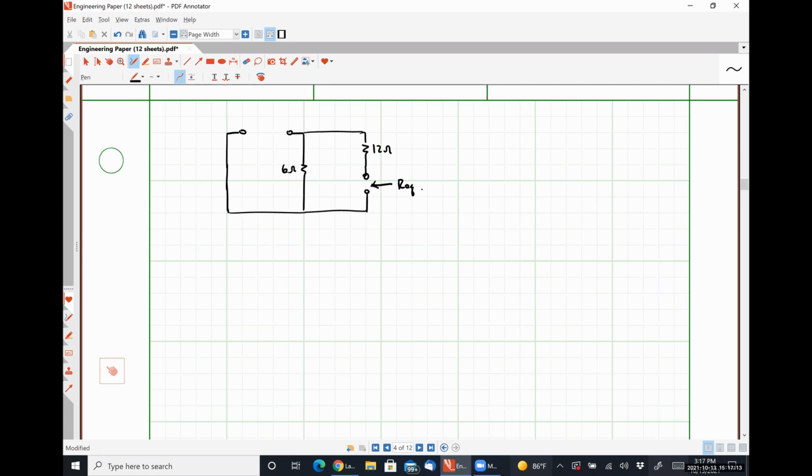And this is what REQ is, because we're trying to see what resistance the inductance sees. So that's going to be the Thevenin equivalent. That's the technique that we will always use to find the equivalent resistance seen by another component.